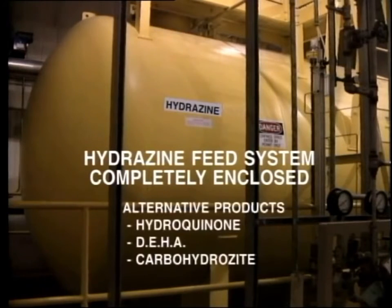Alternative products are available to be used in place of hydrazine, such as hydroquinone, DEHA, carbohydrazide, and others. These substitutes are apparently safer to handle. We have just mentioned that hydrazine volatilizes. Other volatile chemicals may be used in place of phosphate and caustic injection, where the boiler operating pressure is above about 1500 psi. The reason for this is that at high pressure, we wish to keep the solids content in the water as low as possible.